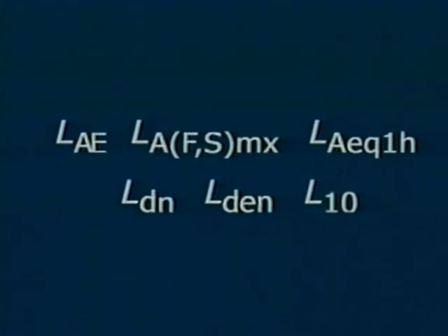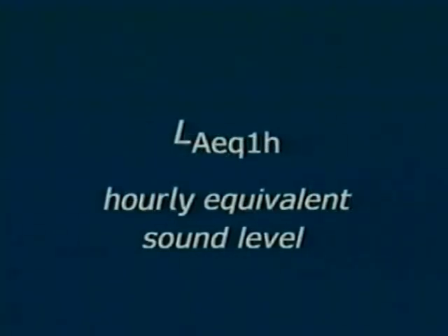While all of these A-weighted noise descriptors can be applied to highway traffic noise, the LAeq1h and L10 are most often used for traffic noise analysis. LAeq1h, called the hourly equivalent sound level, is essentially the average A-weighted sound level occurring during a 1-hour period.